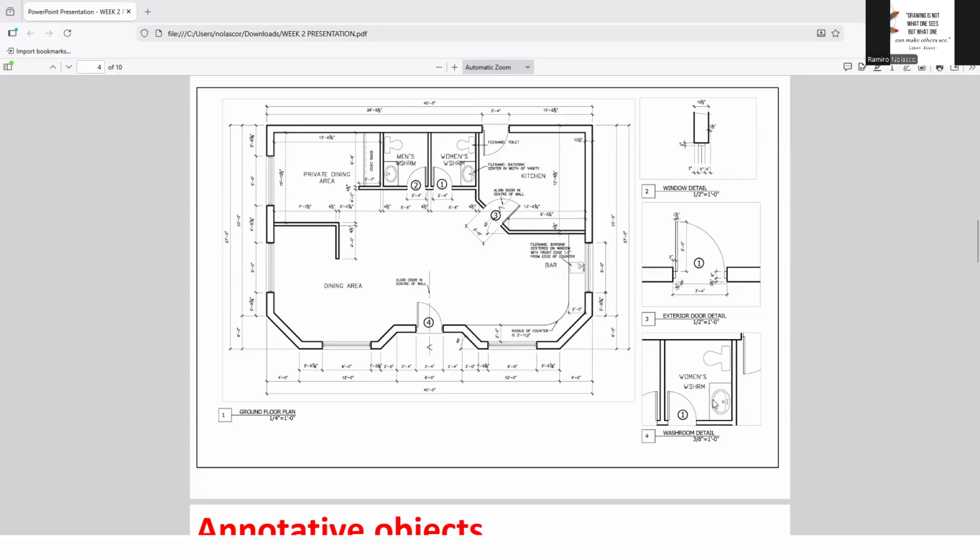And then later, you can add text that will show here and there, but they are the same height. Okay? Why are they the same height? Again, annotative. But now, the text is showing in the same location. So how do we do that? That will be our next lecture, adding text. So for now, just add the dimension as shown.